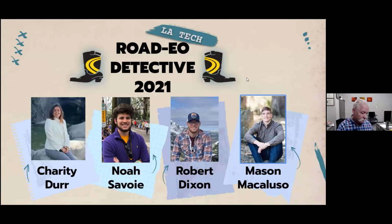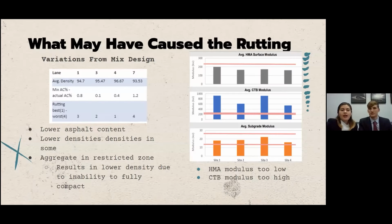This is our 2021 Rodeo Detective team. One of the things that we noticed was that there was a lot of variation from the original mix design. As you can see here, the more variation in the asphalt content, the higher the rutting. So we think that's one of the issues. There were also lower densities in all of the samples. Those lower densities can be the result of one of the aggregates, specifically sieve number 16, being in the restricted zone. Being in the restricted zone means that there are more fine particles, and it doesn't allow the mix to be fully compacted, so that results in a less dense mix.